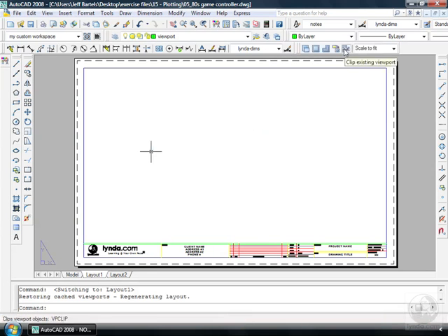And I'll release. Now, good form says that we should cut our viewports on their own layer. Notice I've already created a layer, I've called it viewport, and I've set it current, so I'm practicing good form. Now I can cut the viewport or the hole in my layout by using this button. I'm going to come up and click the single viewport icon.